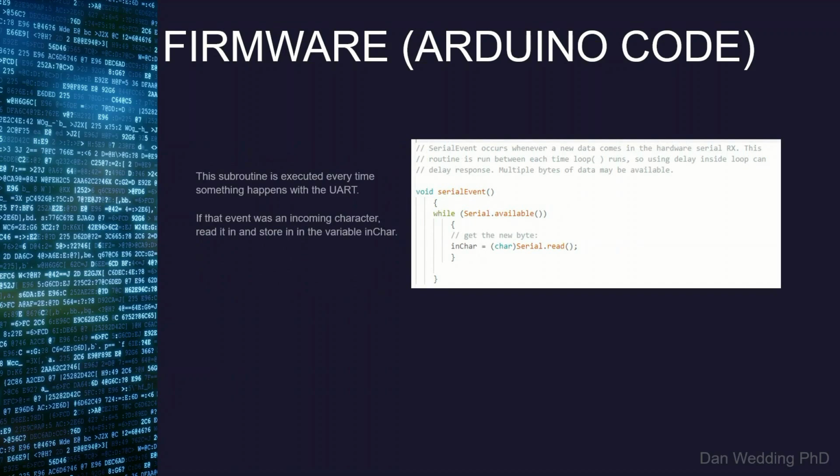This subroutine is executed every time something happens with the UART. If that event was an incoming character, read it in and store it in the variable inchar.